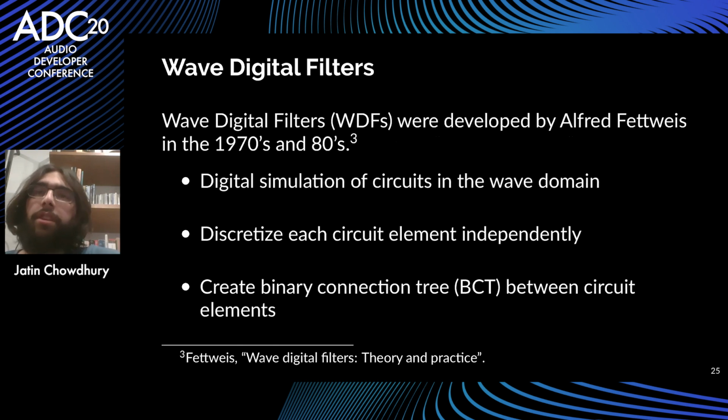So originally, wave digital filters were developed by this fellow named Alfred Fettweis in the 70s and 80s. He basically figured out that you can analyze your circuits in the wave domain. And one nice thing about this, one big advantage of having this free parameter that I talked about, is that you can discretize each circuit element independently.